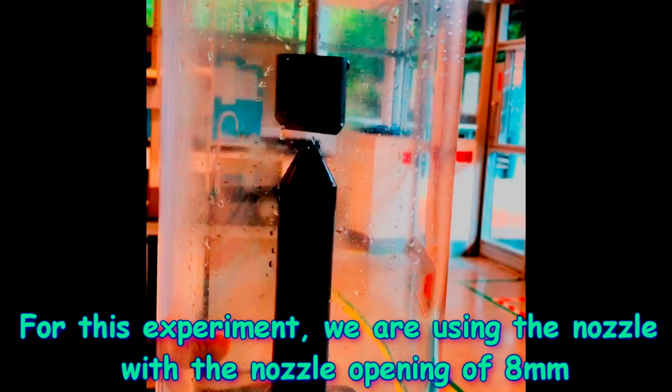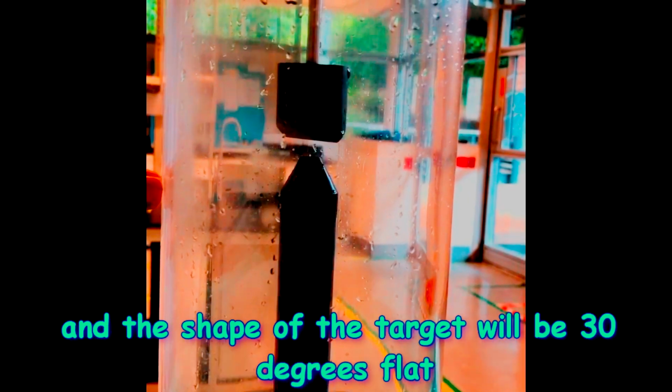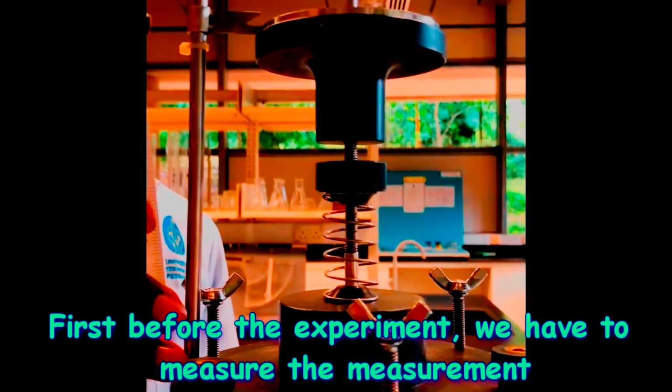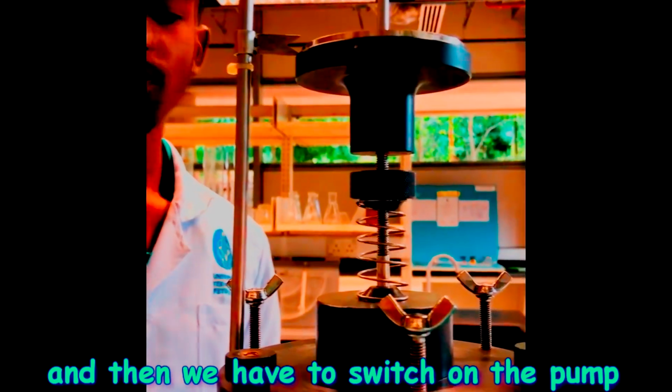For this experiment, we are using the nozzle with the nozzle opening of 8 mm, and the shape of the target will be 30 degrees flat. So first, before the experiment, we have to take the initial measurement, and then we have to turn on the pump.